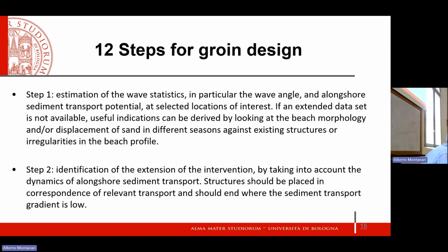You know, when you talk about sediment transport, when you talk about morphology of sediment, of beaches, the experimental verification is the most meaningful thing that you can do. Okay, so the direct experiment. This is why I also suggest, when it's possible, when designing these interventions, to keep flexibility so that you can adapt them later on. Take this flexibility, because the experiment, the direct experiment, is the most advisable situation, because these are phenomena that you understand, describing the hydromorphodynamics. There is a lot of uncertainty.